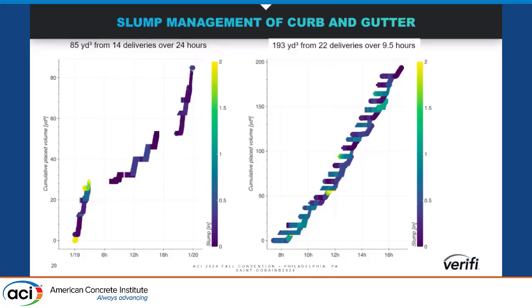Okay, I think this is the last one. This graph looks a little bit weird, but on the x-axis is your time, and on the y-axis is your total volume delivered. Each of these little hockey sticks is a truckload. It starts off flat because I hope they're not discharging on the way to the job. Then it starts to discharge and angle up. So you can clearly see the left side versus the right side if you get your ducks in order.